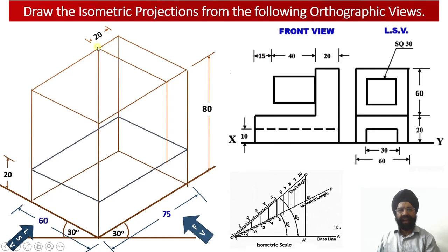And once I draw another vertical projection from this point onto the top surface of the ring over here, this vertical edge of the left hand side view has been obtained. So it means that this square surface having edges 60 millimeter by 60 millimeter has been obtained. We can see that this is 60 millimeter, this is 60, this is 60, and once I join this point with this point, this completes the construction of a square surface over here.